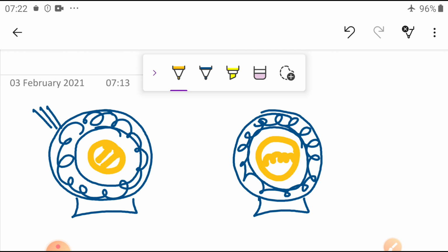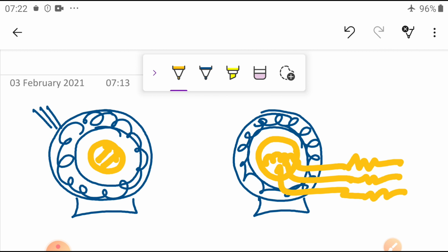These 3 phase windings are connected inside and taken outside with the help of slip rings. But here it is short circuited. Here it is possible to add this one. In this case, I am going to add some resistance initially, so I can add some resistance in this rotor winding.